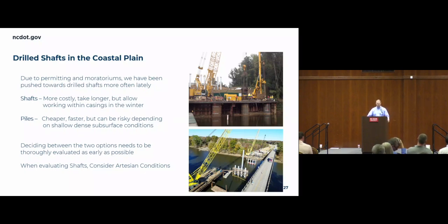We've done a pile investigation plan, a test pile program to determine could we drive through this layer, what is it going to take to get through this layer, and a bunch of soil testing. So that, to a lesser degree, will happen on a lot of projects, but those decisions need to happen early.